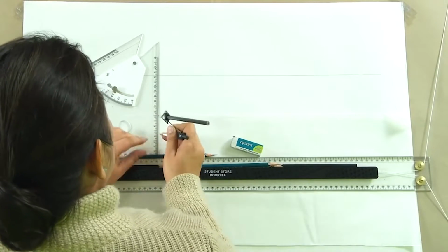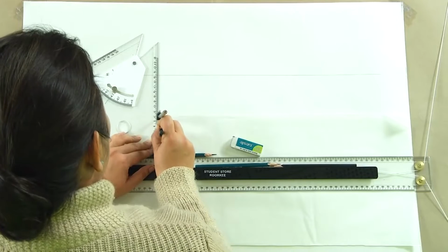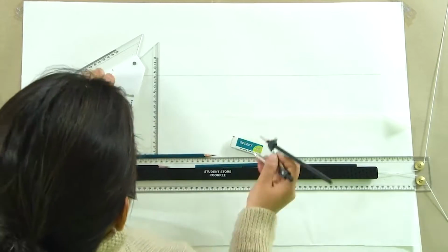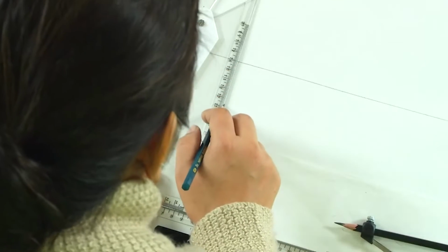So let us quickly look at some examples and try to locate the centers of the spheres. Let us start by drawing the projections of a simple sphere. Here I am assuming that the sphere has a radius of 3 centimeters. Let us assume the first condition, that the sphere is kept on the HP and it has its center 5 centimeters in front of VP. Very simple, we will locate the center of the circle. So it is 5 centimeters in front of VP and it is resting on the HP.